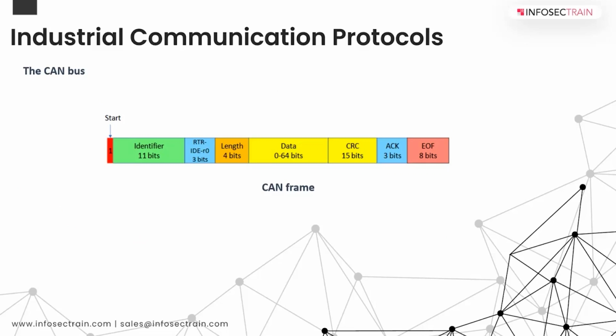So how does CAN work? CAN transmissions operate on the producer consumer model again. When data is transmitted by a CAN device, it concerns another device that is designated by an identifier, and this identifier, which must be unique on the network, also provides the priority of the message.